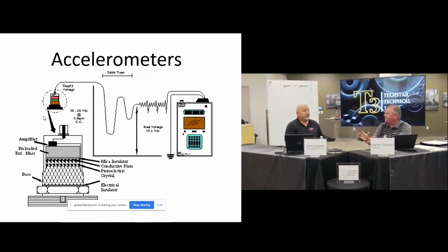So you're looking at those higher frequency applications, like the rolling element ball pass frequencies. A good, hardy, general purpose accelerometer normally costs somewhere around $200 to $300 and has an accuracy of 5%. These are more trustworthy than the ones that are accurate to 15%, but the 15% is going to be cheaper.